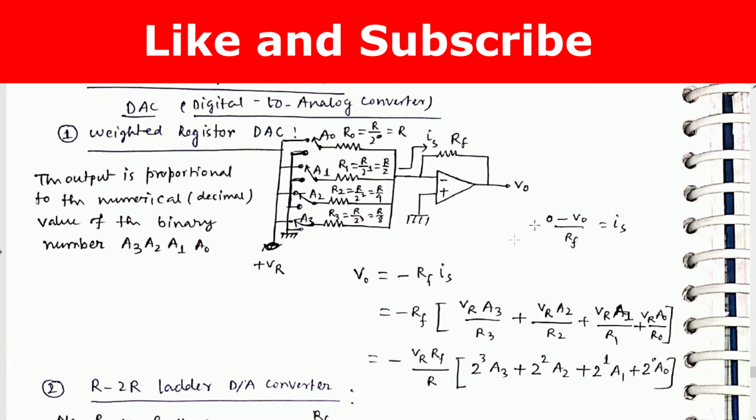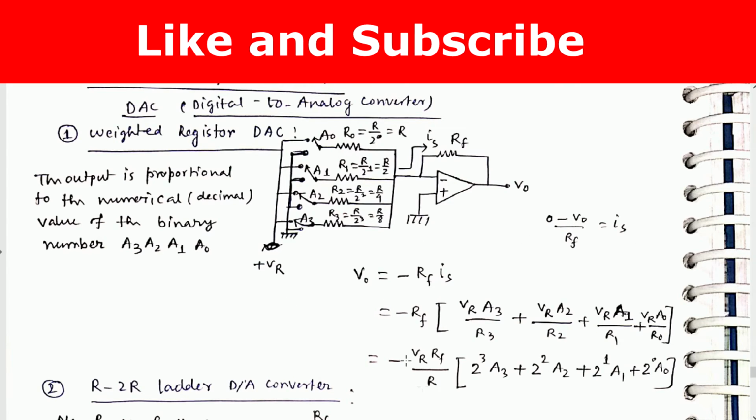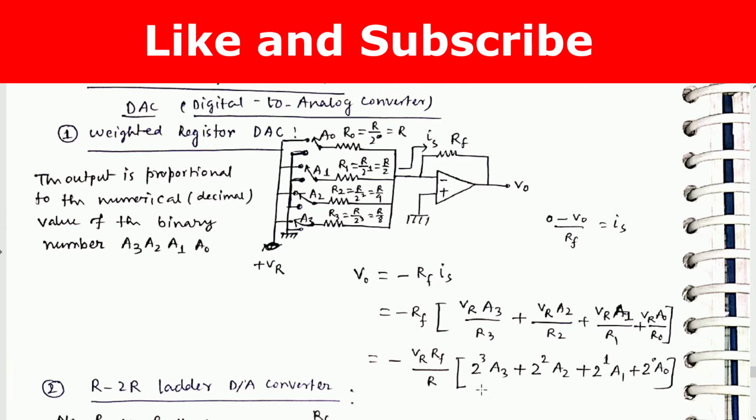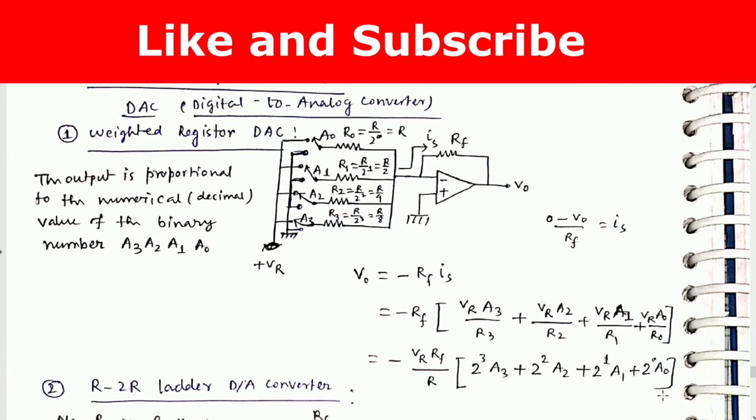This is a reference voltage, and in this way we calculate the output voltage. So remember the final expression: V0 equals minus VR into RF by R, 2 to the power 3 A3 plus 2 to the power 2 A2 plus 2 to the power 1 A1 plus 2 to the power 0 A0.